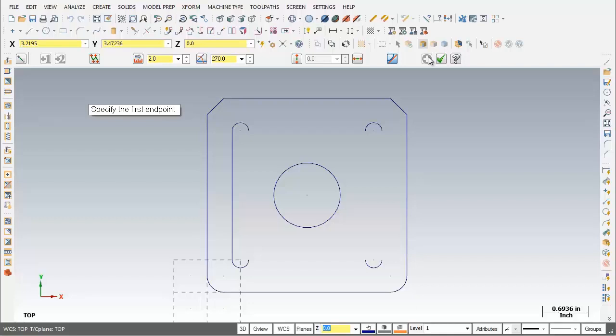So when you need to create lines that are tangent to arcs or circles, and the tangency point is not the endpoint of the arc, what you can do is hold down the Alt key to disable the AutoCursor, and at the same time pick the arc in the approximate tangency position. Now for the creation of these 4 tangent lines, you can employ either method. Snap to the endpoints or disable the AutoCursor to explicitly use tangency.